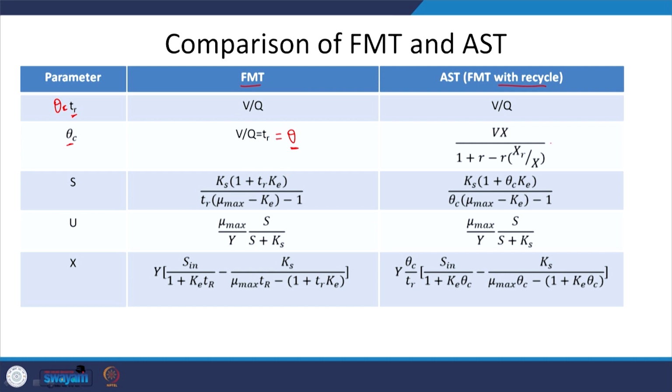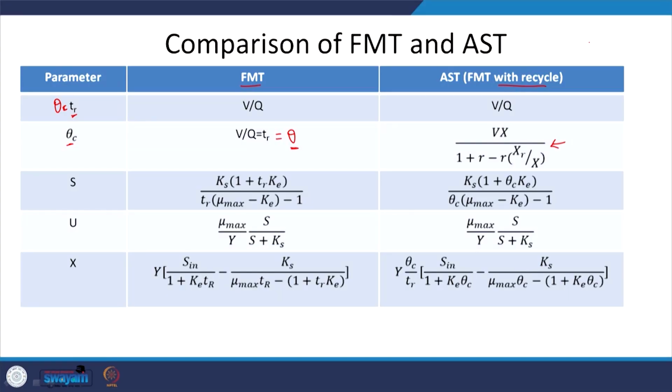But with recycle, we are increasing theta C, meaning we are increasing the time that the microbes are present in the system, so the microbes have more time to degrade the organics. Thus, the efficiency of the process is going to increase. Again, this is from the MIT open courseware, so they would have used slightly different variables, but we do not need to go into that in detail right now.